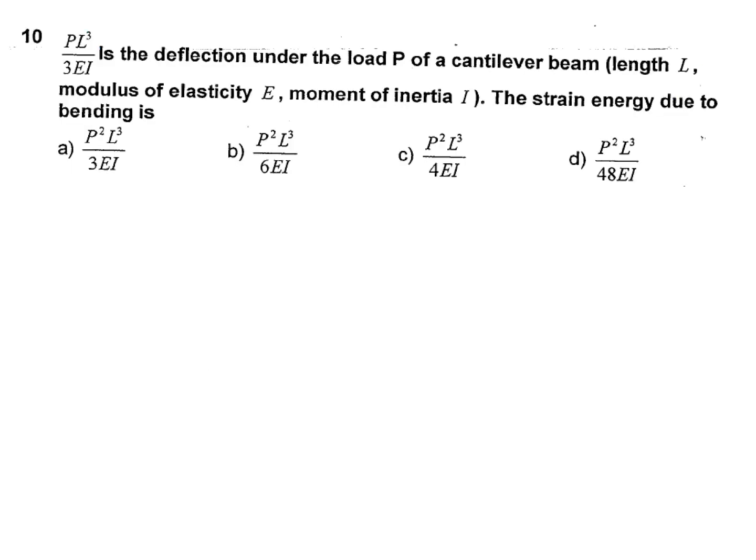Question: PL cubed by 3EI is the deflection under the load P of a cantilever beam of length L, modulus of elasticity E, moment of inertia I. The strain energy due to bending is dash. Data given: deflection is PL cubed by 3EI.